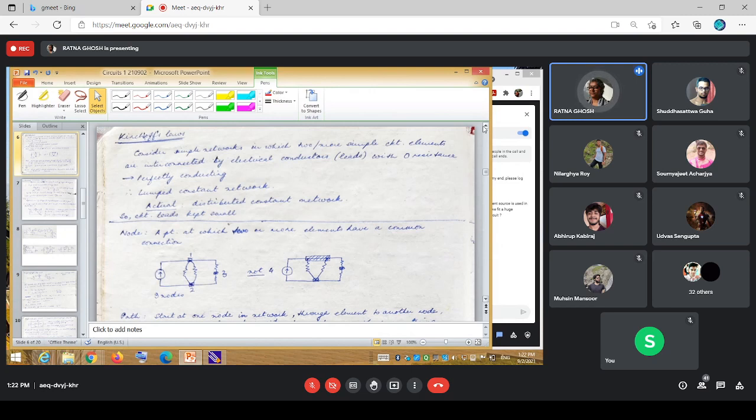Or KCL, in the larger context, you could think of it as a conservation of momentum principle. So that's actually the through variable. If you think of the through variable and the conservation law in terms of the through variable, that is nothing but the conservation of momentum principle. But it is essentially conservation of charge at a particular node. So Kirchhoff's laws are essentially conservation laws. And before we go on into Kirchhoff's laws, let me talk about this particular concept, that of lumped constants.